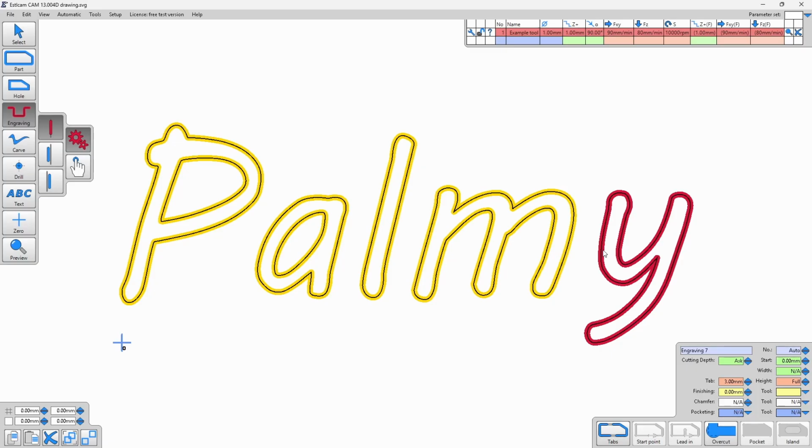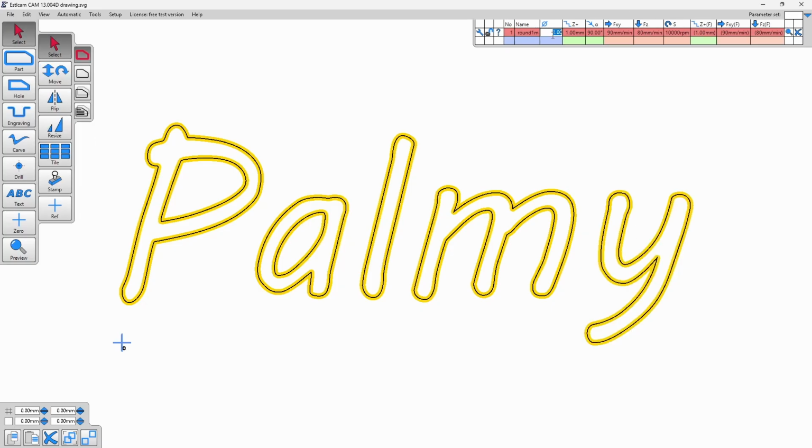After that, we just got to go up to the top and change all of our tool properties. So where it says number, name, and it's got all those little icons up at the very top, that's where we change our tool properties. You can add more than one tool in case your CNC machine can change tools. So first, if you want to change the name of this particular tool, give it a name that you like, and then what is the size.